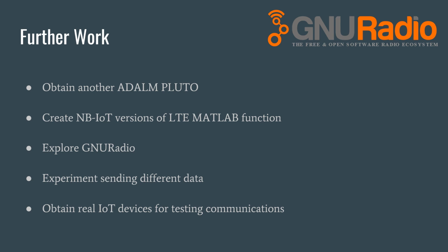The LTE toolbox has built-in cell search and frequency offset functions. These are not suitable for the NB-IoT application because they adhere to the traditional LTE standards. The major feature being that the functions only accept a minimum of 6 resource blocks due to the differences in control signals. GNU Radio is another direction the work could be taken.